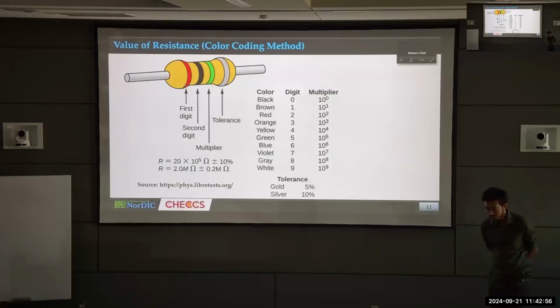I will spend time testing for those fancy exact resistors. So it's going to cost you money. You're better off just buying off-the-shelf components and living with the 5% or 10% tolerance. Otherwise, if you start to look for tighter tolerance, you have to pay more.